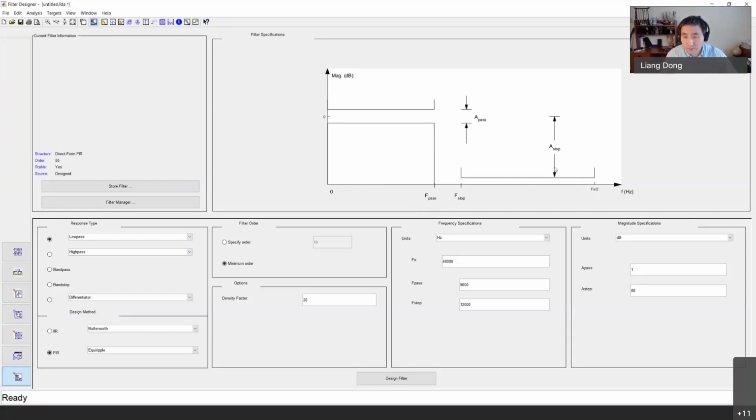Here, this is the stop band ripple. So that's the stop band ripple divided by the highest peak that I have. There are different ways we define that. In Matlab, some of the Matlab code, instead of using the highest 1 plus delta 1, it used the middle sign here. It used the median sign here. So that is 0 dB in this case.